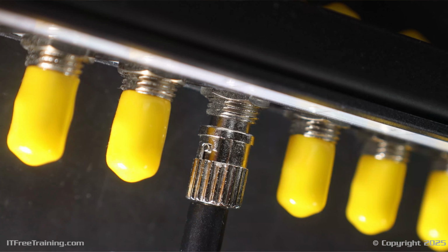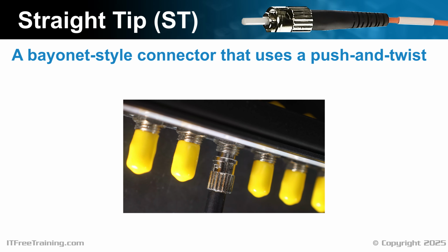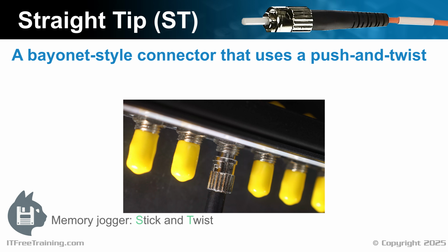If you have trouble getting the connector to go in, it is probably because the protruding edge is not lined up with the recessed area, so twist the cable around until it does. The main thing with this connector is to remember the abbreviation ST. For this connector, I use the memory jogger stick and twist.